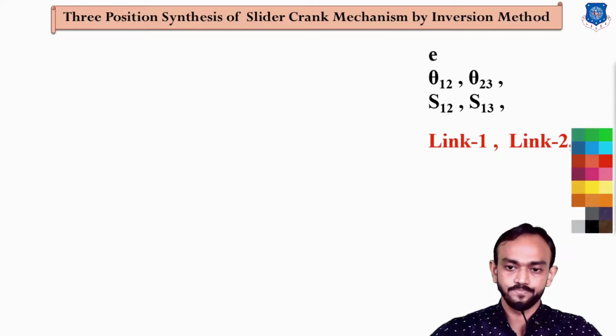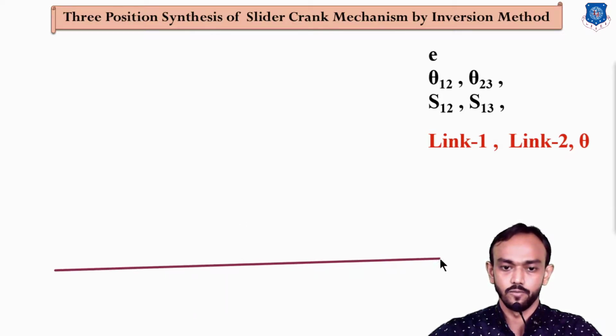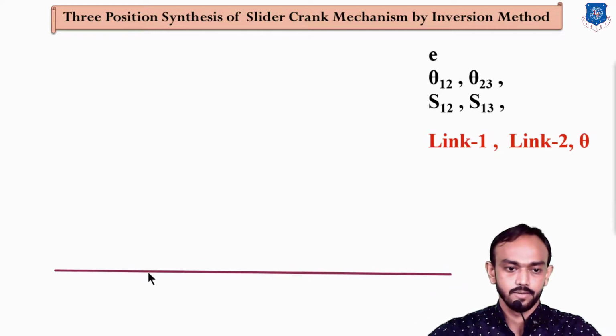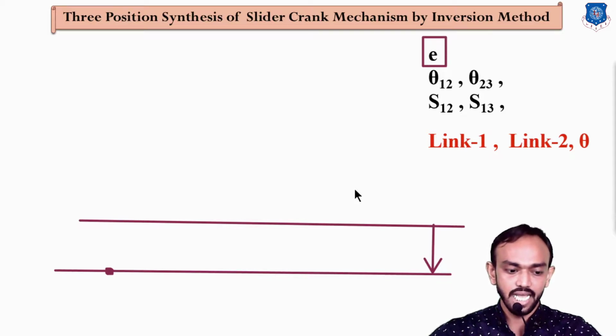So start with this. First of all, 2 parallel lines. First of all, one is for the center of crank. I am going to put the center of crank here, and a second parallel line, and the distance between these two is E, already given, the eccentricity is given. After that, I will make another point on this line randomly. Okay, this is for the first position,